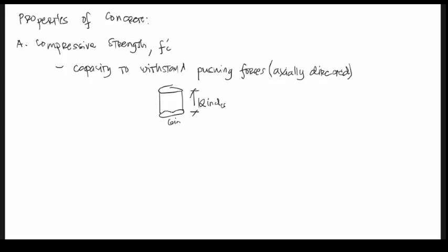Ilalagay mo siya sa compression machine, lalagyan mo siya ng compressive strength. So, iipitin siya dun sa compression machine hanggang sa mag-fail. When we say mag-fail, yung iba mabibitak, or basta na lang hihinto yung compression machine. So, kunwari, ang binasa ng compression machine ay 17 MPa. So, that will be the compressive strength of the material. So, ganun ang pag-determine ng compressive strength, hindi actual. So, this is tested at 28th day. So, at 28th day, itetest mo yung concrete cylinder mo.